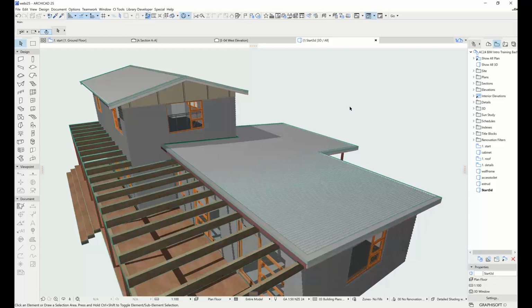In almost all cases, that will migrate properly from your ArchiCAD 24 project. It should just come through looking exactly like it did in 24, although in some cases it may not. There are certain types of edge or edge configuration that the covering tool, when migrating from 24 to 25, doesn't do correctly the first time off, because the tool has to make certain assumptions about how the edge types are going to work. If you do encounter that when doing a migration from 24 to 25, we have a built-in way to fix those sorts of issues.